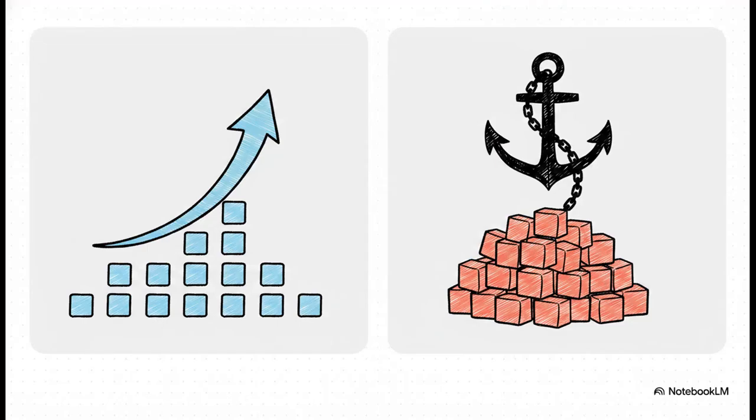Imagine the best case scenario, zero variability. Everything is perfect. You hit maximum throughput with the lowest possible cycle time. If your WIP is at or below that critical WIP we mentioned, your cycle time is just the raw process time. Nothing waits. It's beautiful.